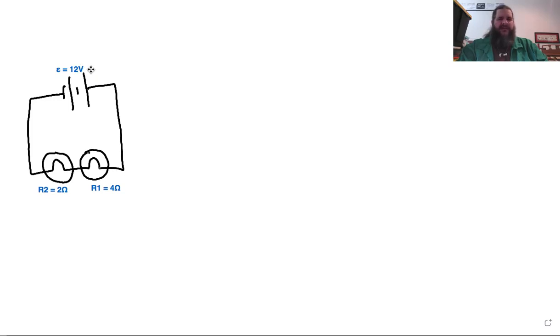So in a case like that, if you know all of those values and you connect them together with a wire like this, what else do you think we'd be able to solve for here? Current, using the loop rule. Yeah. And since there's only one path, it's just a single loop, what does that tell you about the current in this? Current should be the same.